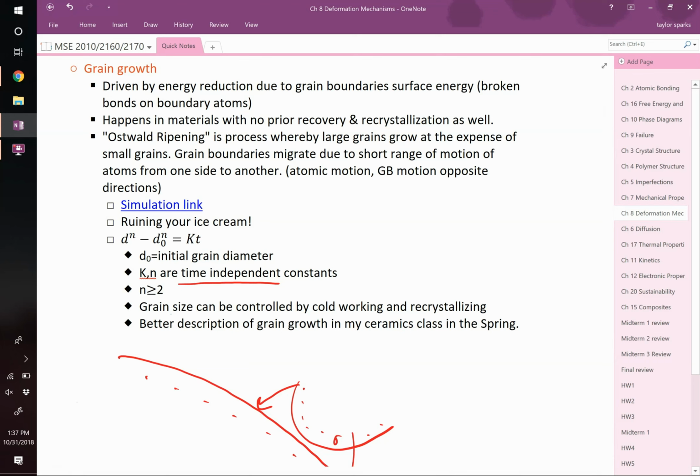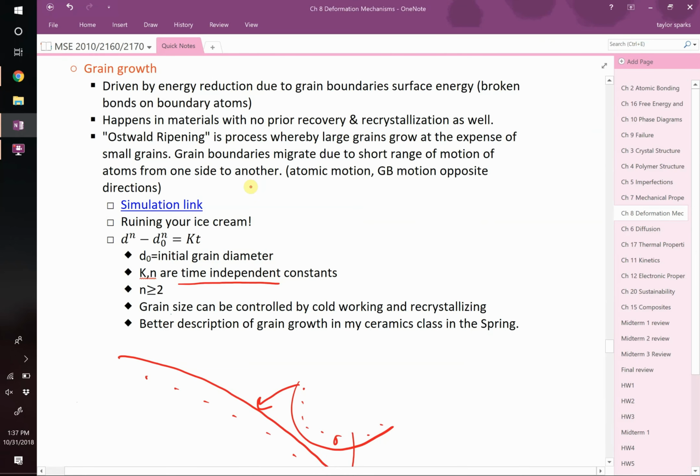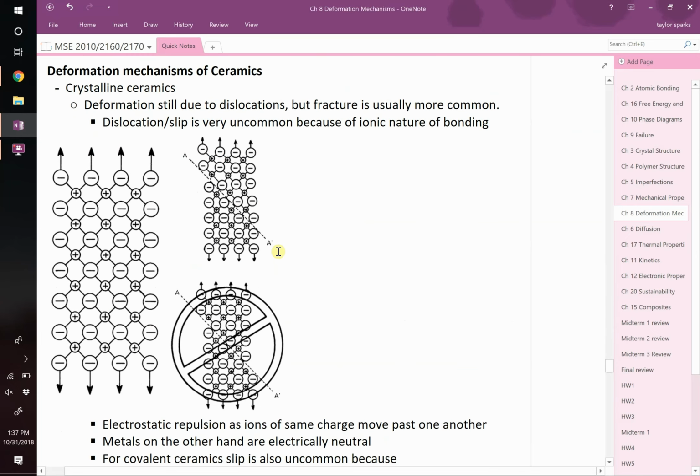And if you understand what they are in a material, like let's say a simulation expert generated those values from matching experimental data to simulated data, all of a sudden now you can understand what your heat treatment will do in terms of growing your grain size, which is a powerful thing to know since it relates to strength and everything else. Okay.